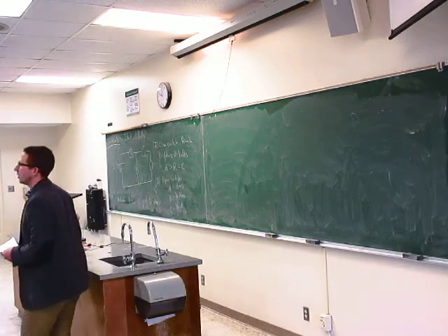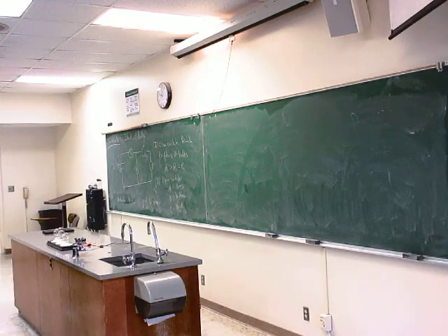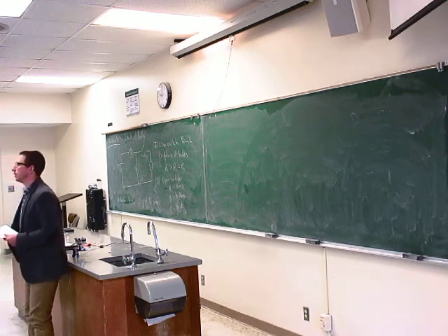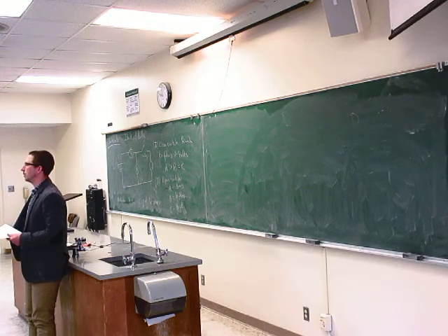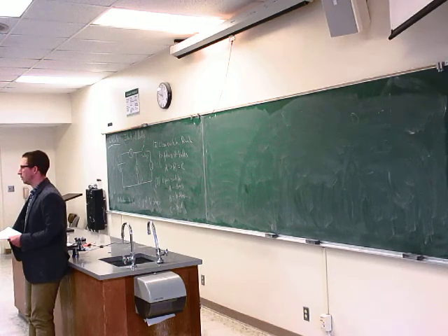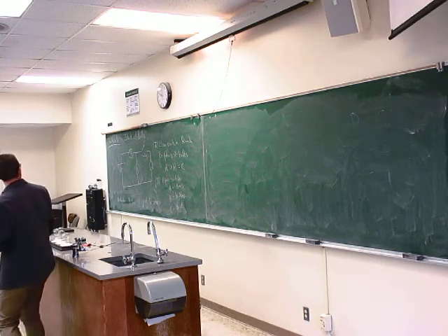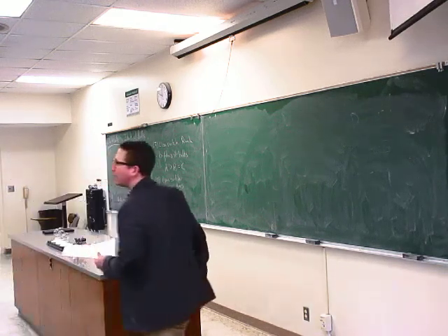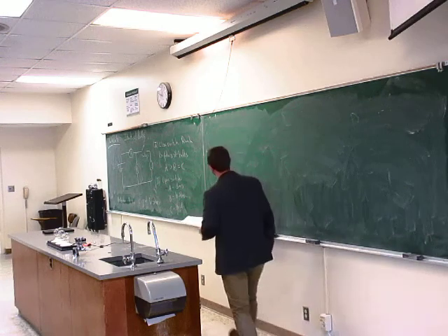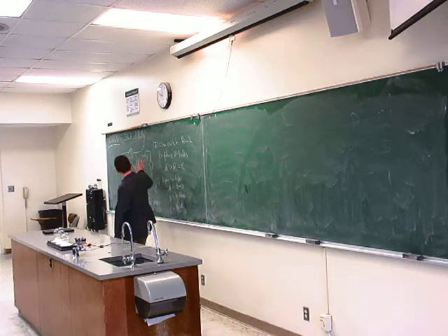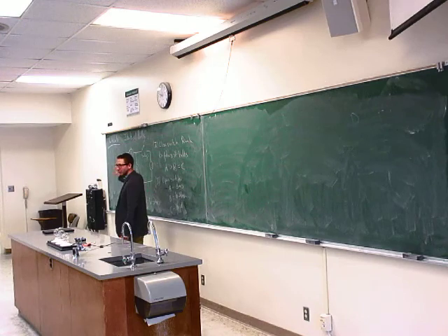Yes. So, well, the overall current in the circuit goes down because the resistance goes up. It no longer has to share current with C, which would have doubled its current, but the overall current went down by a factor less than double, so the overall current to B still went up, and since current's part of the power equation, the brightness went up. So you're saying the current went down by a factor that was greater than 1/2, or less than 1/2? Less than. Less than 1/2. How do you know that?